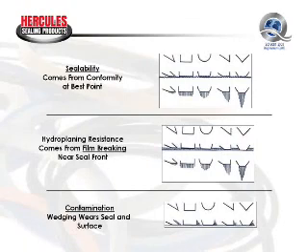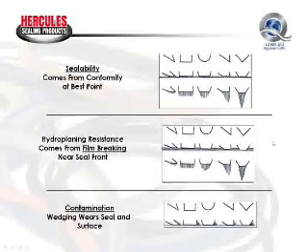If you are using two B-lips on a double-acting piston with the loaded U-seals, you need to remove one of the energizers from one of the seals. That will help reduce the low-pressure sealing capability of that seal so it minimizes the opportunity for trapping pressure. It has no effect on the high-pressure sealability of that seal. It only reduces the low-pressure sealability.